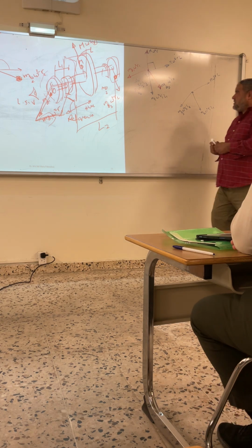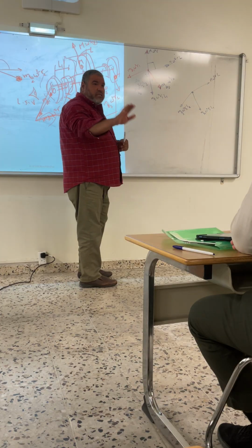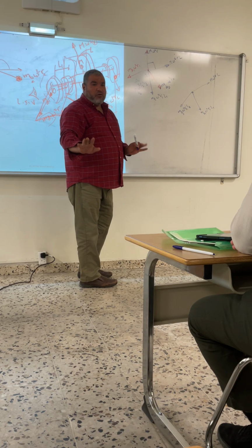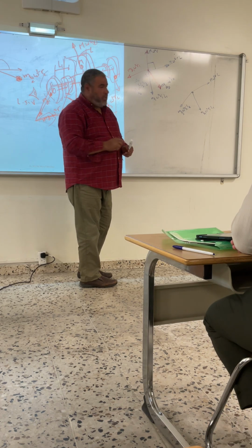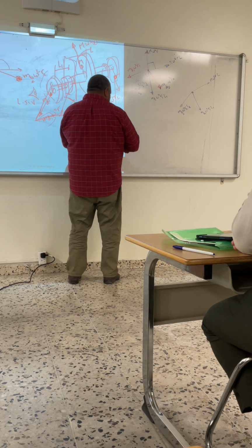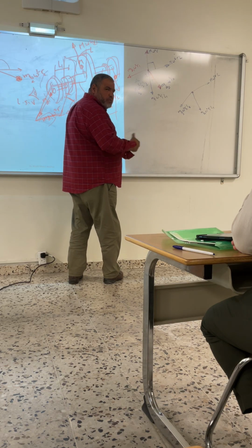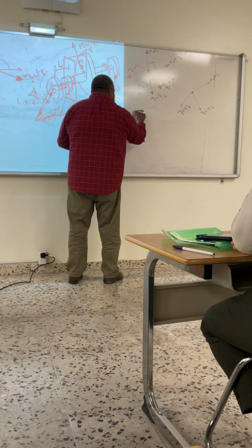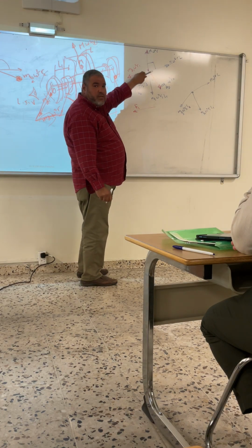Now guys, let's assume that you already drew the force diagram, and I'm going to follow up all these red colors. And I'm assuming that the force is in complete balance. What do I mean by complete balance? Zero. Wherever you started from, you should end up at. For example, using of course the scale and all this business that we did earlier, let's call this F1, to make it short, which represents MB1 omega square R1.